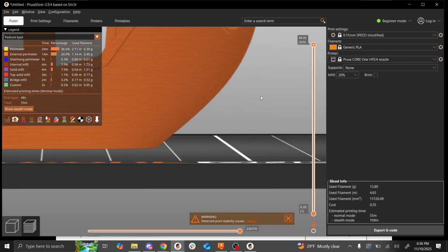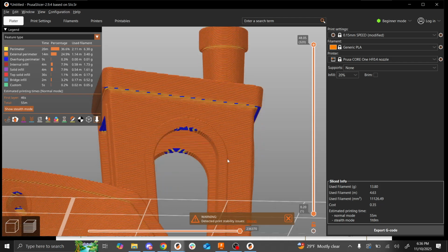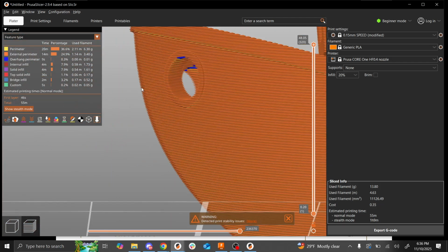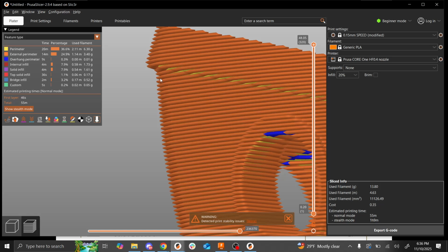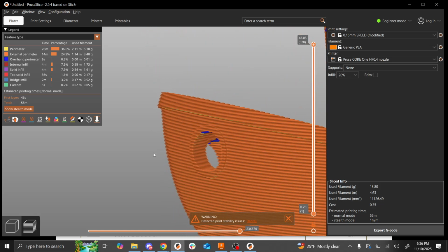So you can see up here where the overhang is very shallow, there's a very large amount of overlap between each layer, right? For reference, most 3D printers come standard with a 0.4 millimeter nozzle. So there's a very small offset here and the printer's not really printing in midair. Maybe 10 or 20% of the extruded material is printing in free space, but the rest of the material can hold it up and it can still print pretty well.